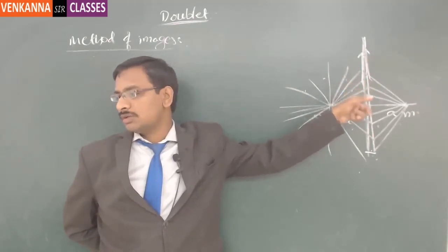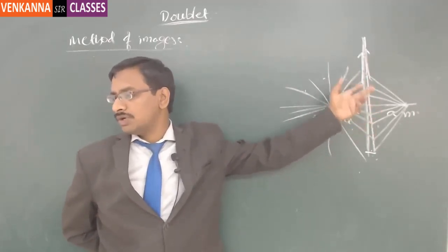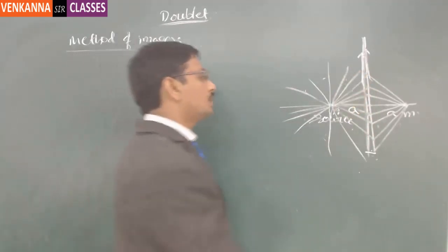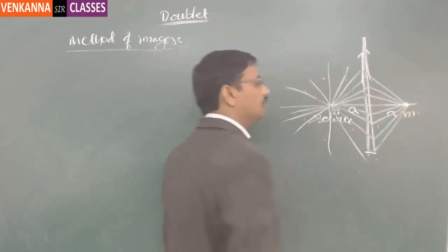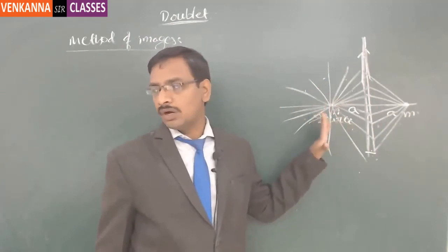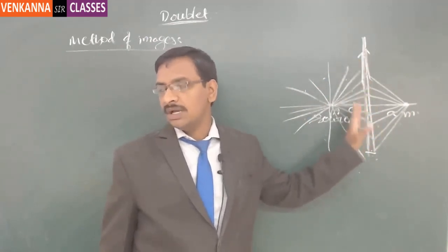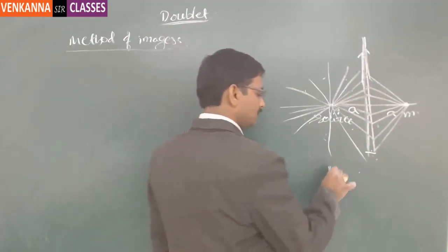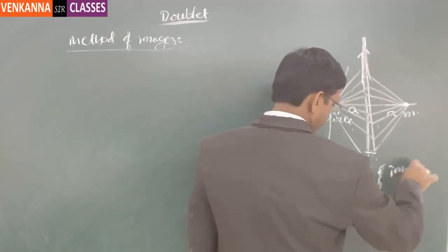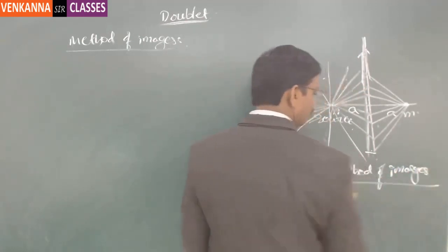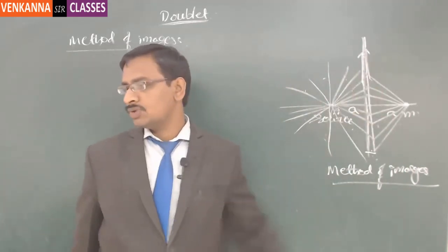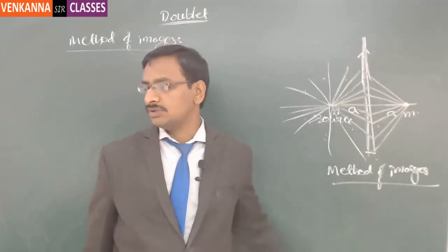So from the mathematical point of view, you wanted to assure that the flow is perfect even here also. For that, you are going to introduce one more source at this location, because there is a source present at this point, so that my analysis will not go wrong anywhere, even if there is a wall present. And this method we call the method of images. So you are introducing the image. So this is the source and that is the image of the source. So treat this as the mirror and then introduce the image there.